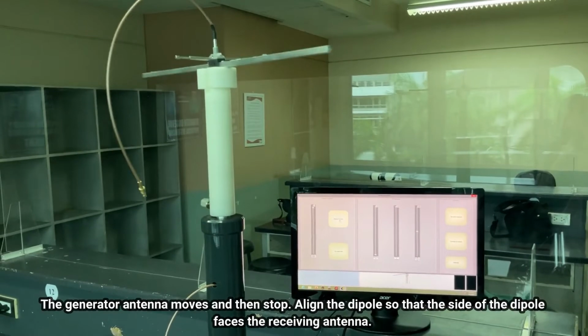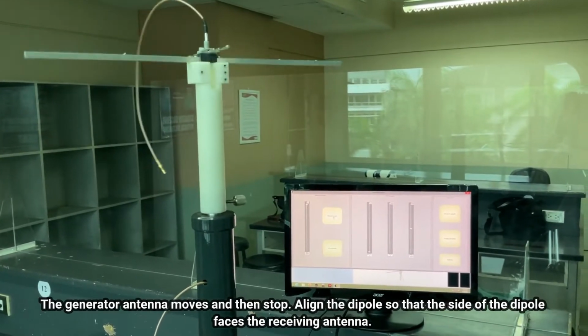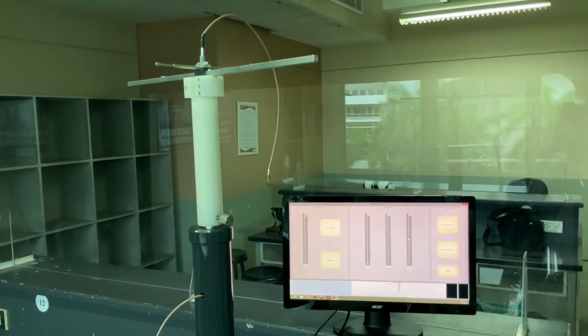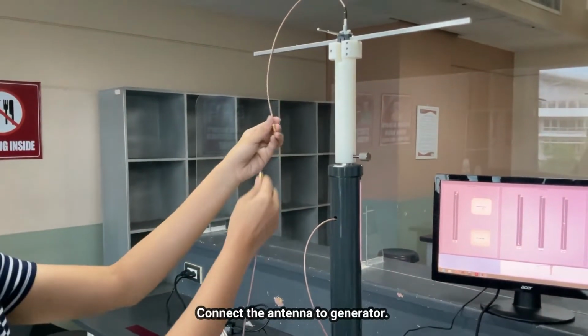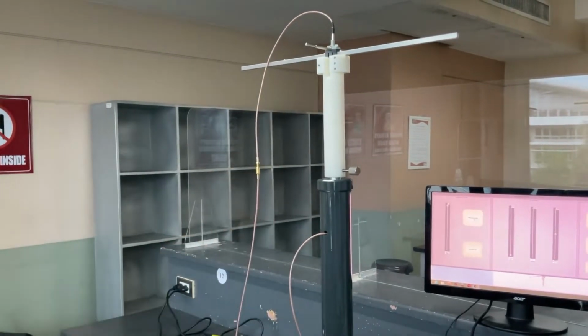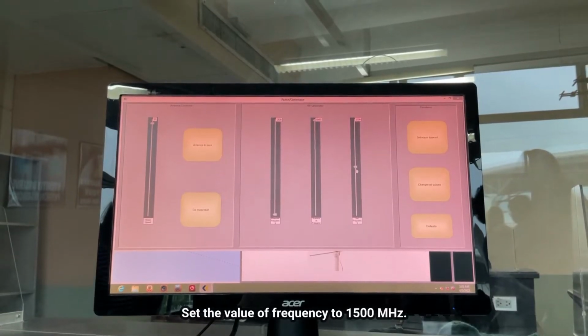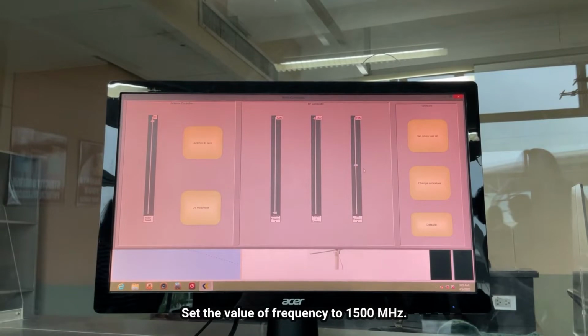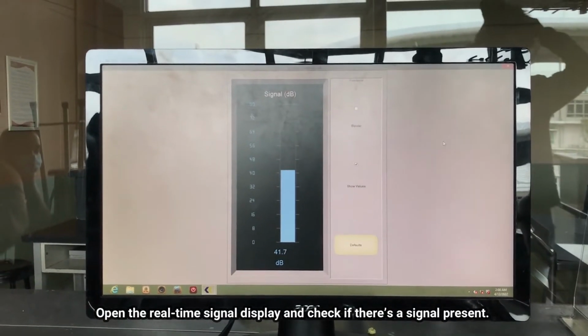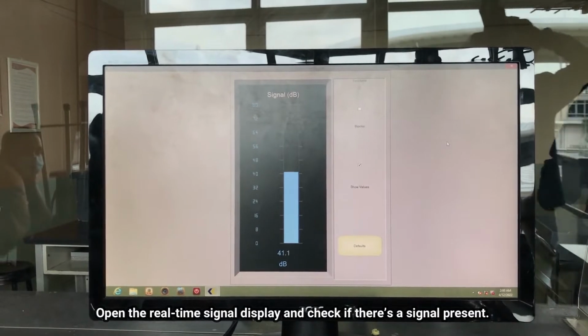Align the dipole so that the side of the dipole faces the receiving antenna. Connect the coaxial cables of the dipole and generator. Set the value of frequency to the default value of 1500 MHz. Open the real-time signal display and check if there's a signal present.